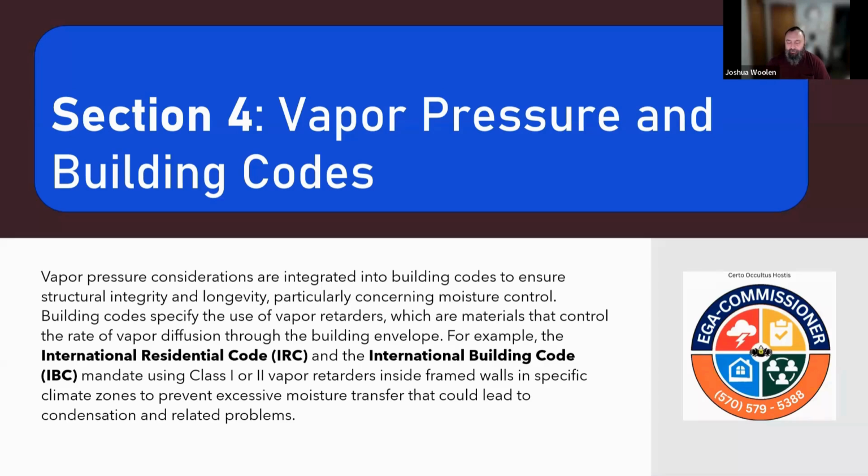And so we have to know these things when we are drying a building, because we may have to remove drywall so that we can dry out the insulation, or just remove the insulation. And we need to be aware of those environments that are being produced and how that is being brought in with the vapor codes and how the contractor is building things for us.